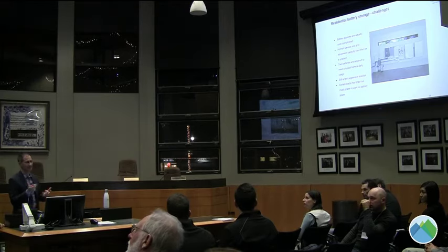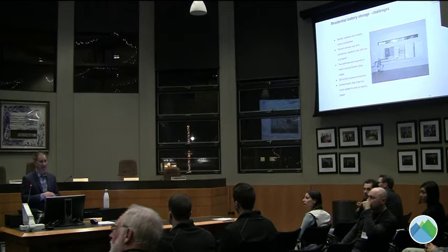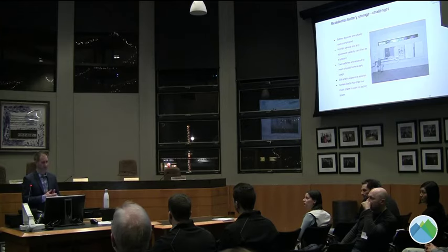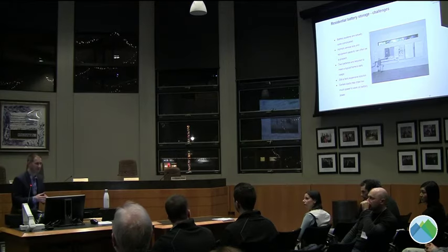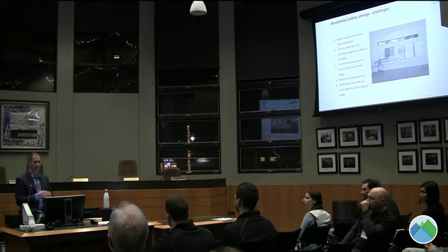The other thing is it turns out quite often the electrical system in the home has capacity issues. I mentioned 2 batteries might be required already to do at home, and it's still fairly expensive. You might be looking at about $17,000 for a single battery, fully installed. The final one is there may be certain loads in your home that are just too big, too sudden, to be able to be handled by the inverters that are in the battery systems.